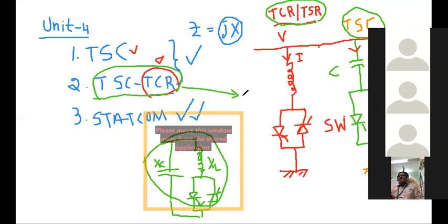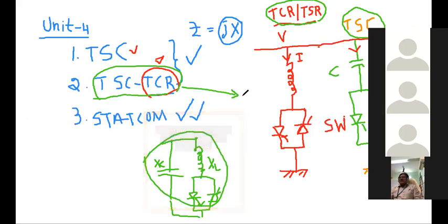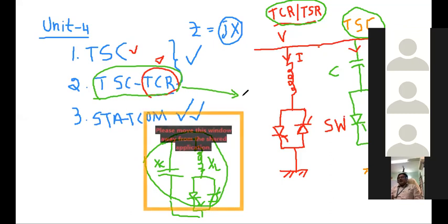Okay. So in the synchronization experiment of the synchronous machine, we make the voltage equal to the terminal voltage, the frequency equal to the frequency of the supply, and the phase sequence the same as that of the grid power supply, and then we close the synchronizing switch. Once the alternator is synchronized to the infinite bus bar, then even if you change the excitation or the field winding of the motor, that is input, or change the mechanical power, the speed and the voltage won't change, because it is directly connected to the infinite bus bar.